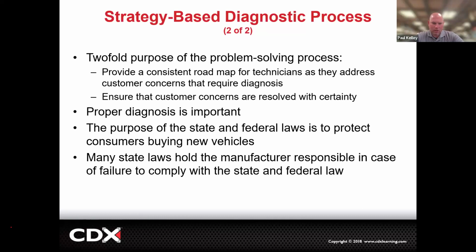Let's say that the customer said the AC blew warm sometimes and the tech drove it and it worked okay, and then tried again tomorrow and it worked okay, and tried again the next day and it worked okay. That vehicle being in the shop for those 3 days is not good, right? So now let's say it's even worse. They drove it 3 times, it doesn't work. You're like, you know what? Hey, I don't know what's up with it. Let's just replace the compressor. You replace the compressor, ship it back to the customer. They say, hey, 2 days later, it wasn't working again. I hit a bump and it works, and I hit a bump and it doesn't work. You put a compressor in.